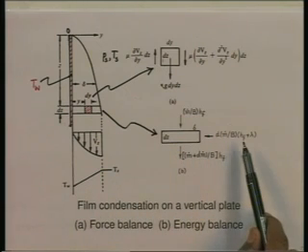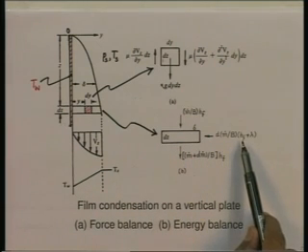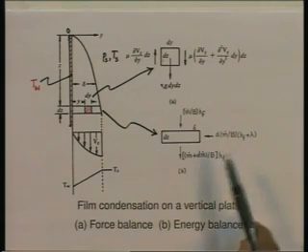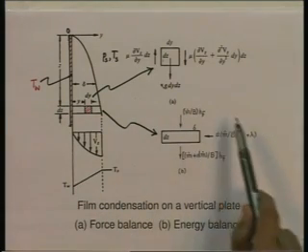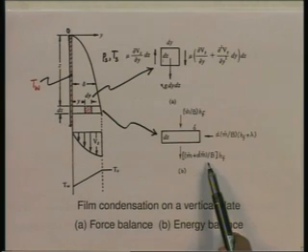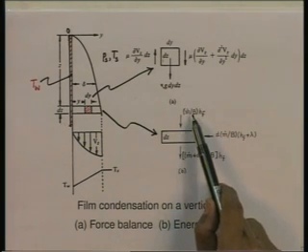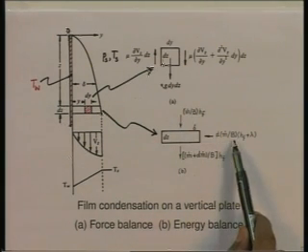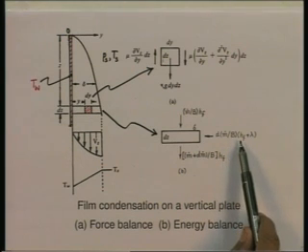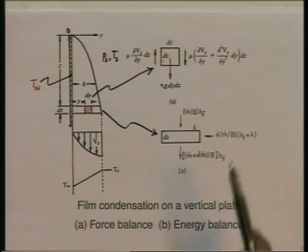So, it brings with it enthalpy per unit mass H f plus lambda, lambda being the latent heat of vaporization. So, this is our enthalpy balance. This is the enthalpy flowing out, this is the enthalpy flowing in at the section Z, this is the enthalpy flowing in at the liquid vapor interface, because vapor is condensing at the interface.